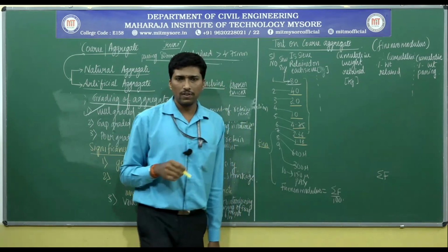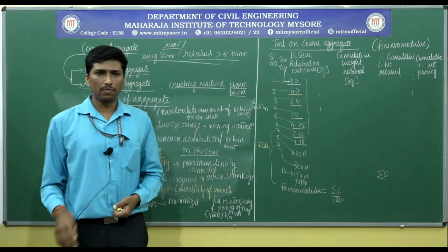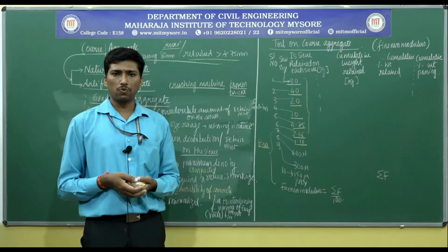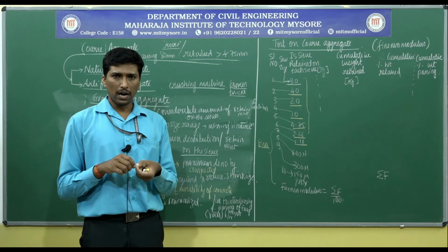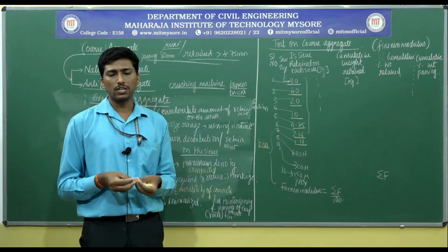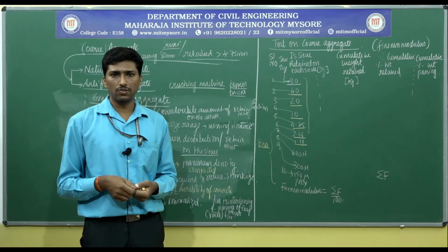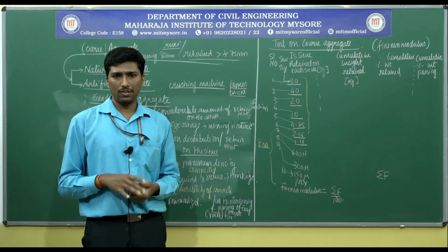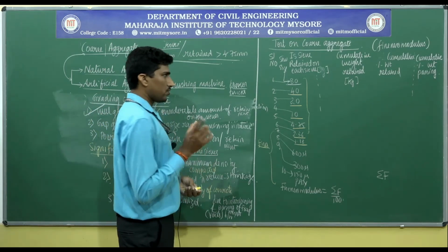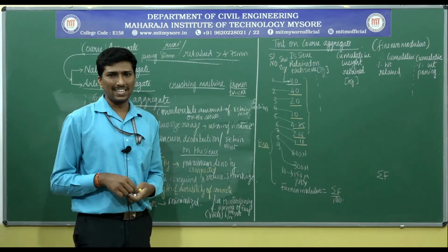Meanwhile, you need to think that even in the deposition of the coarse aggregate, where they have a cone type of deposition, due to the abrasion as well as the impaction, the particles have a limited load capacity, they tend to set up a crack, and later on disintegrate into smaller fragment particles. That has to be minimized in the on-site facilities. That is where we call it storage of the coarse aggregate and its maintenance.